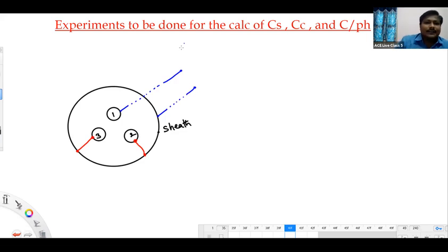Okay, listen. After taking this cable to the lab, for example, if it's a 3-phase cable with a rated voltage of 11 kV, we are not applying 11 kV to it. We are just taking a piece of cable to the lab without any supply, connecting core 2 to sheath and core 3 to sheath, and measuring the capacitance between core 1 and sheath. How to measure capacitance in the lab? Maybe by using some Schering bridge. We'll get some number for the capacitance.